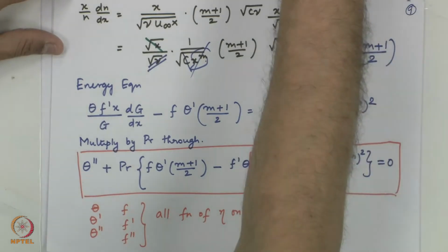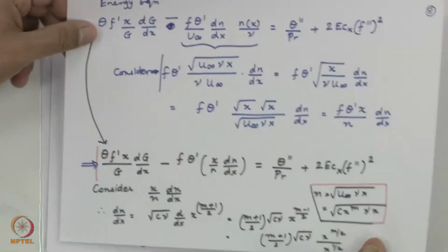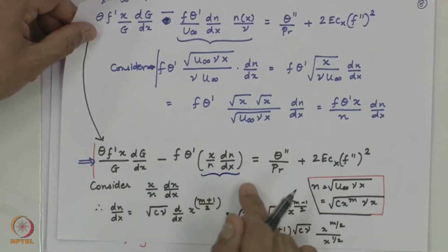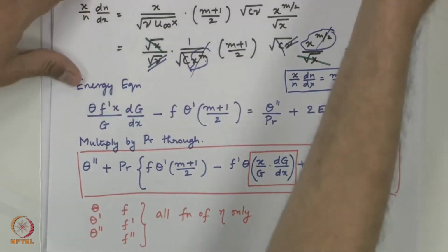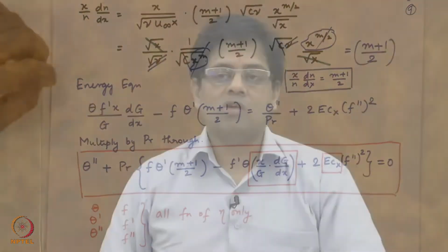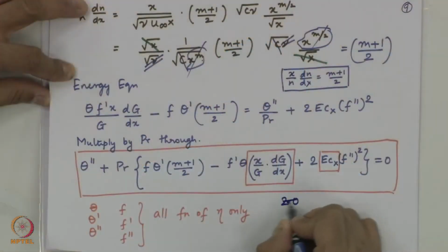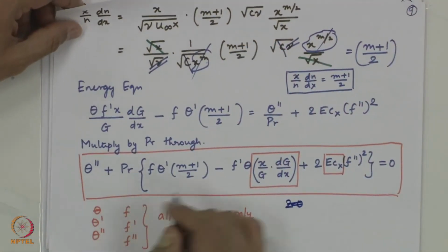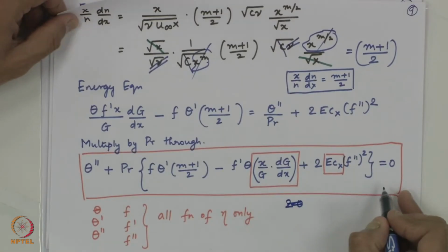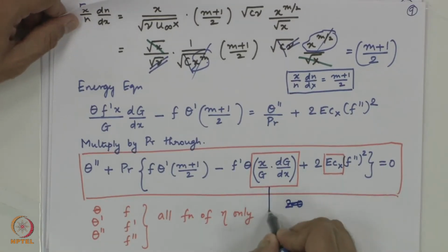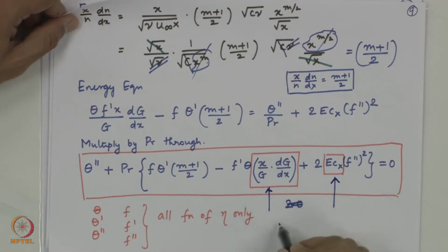So we substituted this here. This term was a part of here, we substituted for this, regrouped the terms, and we got this differential equation. And we went on to argue that for this differential equation, of course, there are two boundary conditions. This is a second order ODE, so I'll write the boundary conditions later. For this to have a similarity solution, this quantity and this quantity should only be constants. We should not have any x dependency in the final form.